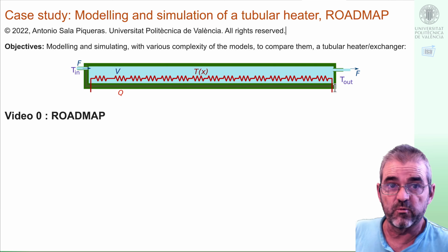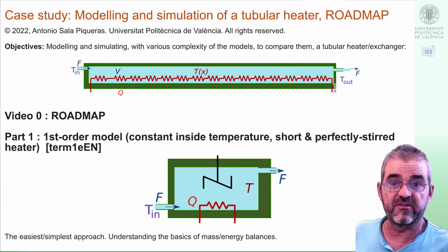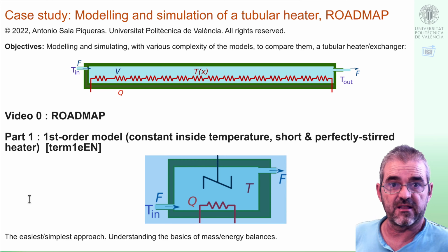In particular, we will start with a first explanation of, let's say, the most simple approach, a tank full of hot water in which all the water is at exactly the same temperature. So we'll understand the basic behavior and the energy and mass balances in there.